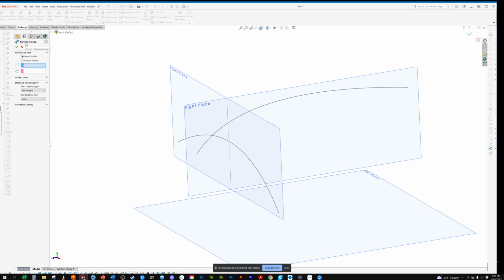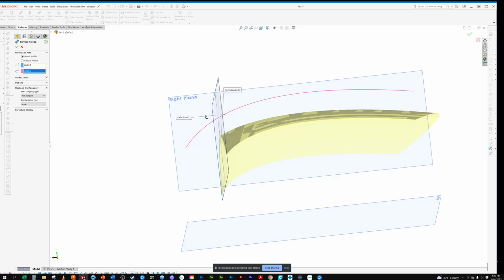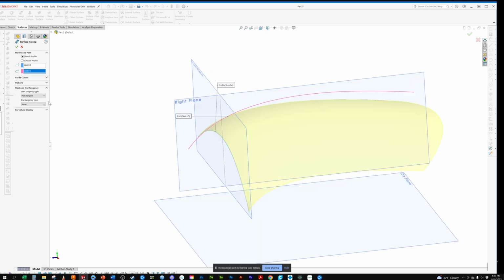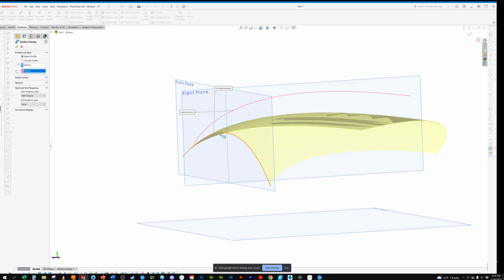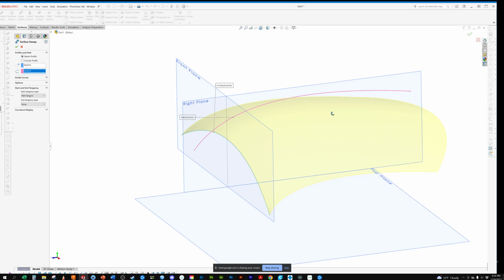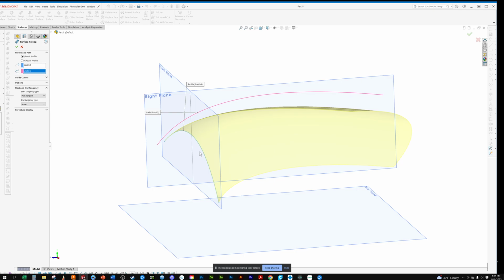We have a sketch profile, which we're going to use, and then we have a path. Now what you can see is they're not touching, and it's determining which one is following along the line. So here we said this is the profile, and we want the profile to remain there, and we want it to follow this path. We only have control at this end again, and the path that it follows.